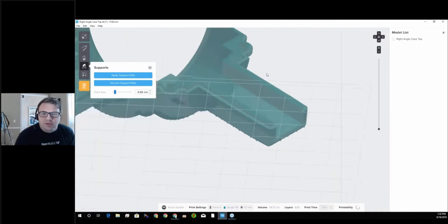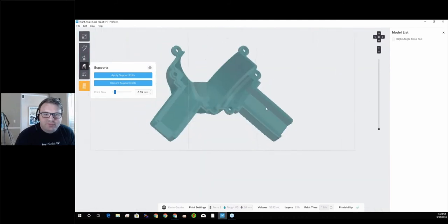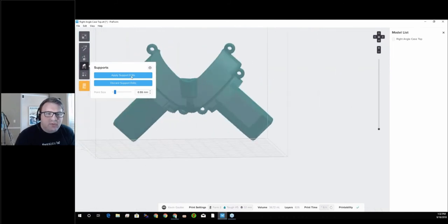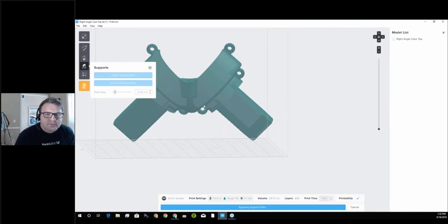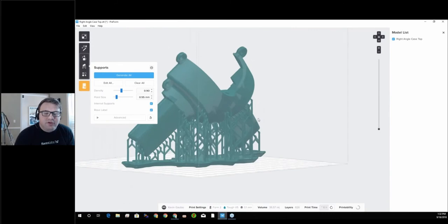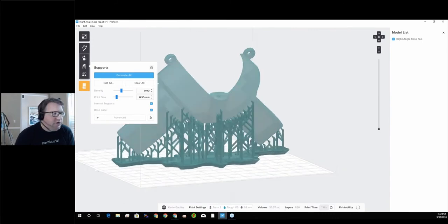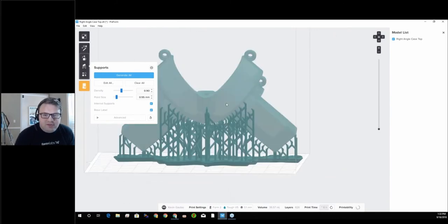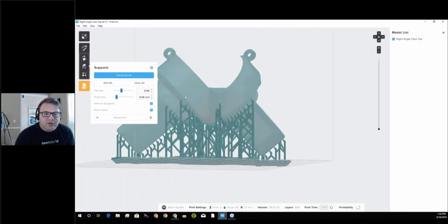Going to get all support points off any critical surfaces. So that's good, and we'll just apply those edits. Next thing is clean up any redundant supports that are just really unnecessary. Once you start getting to more vertical faces, you really don't need supports running up the sides of them.